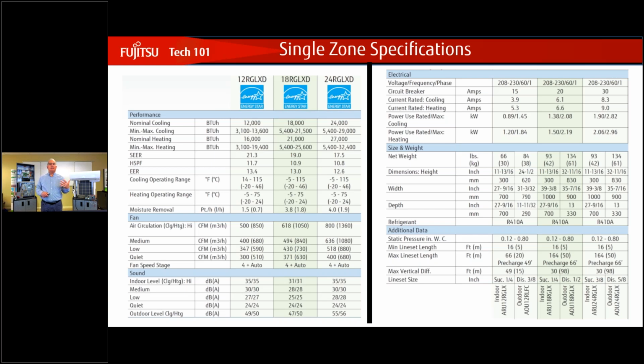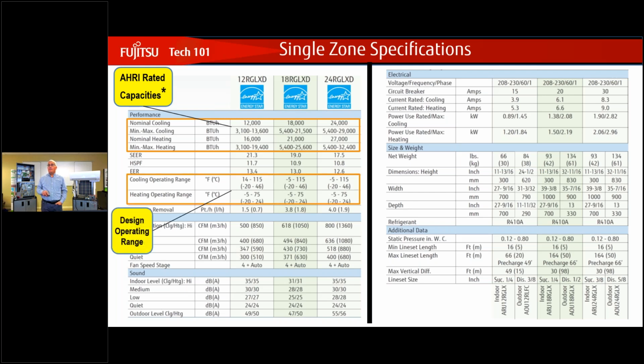If I'm going to size it, I need to do my calculations, and I need from my design and tech manual the page for heating and cooling based on different outdoor temperatures and whatever I want to keep indoor. That will tell me the BTU that the unit can put out for heat and or cooling, and now I can size my equipment properly. All right, so again, those are ratings up there, just where the equipment plays. That's not to use for sizing, okay?